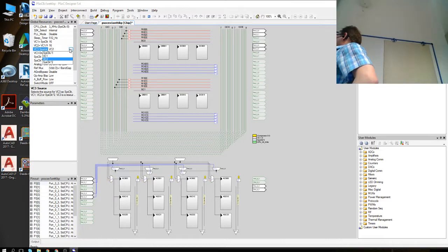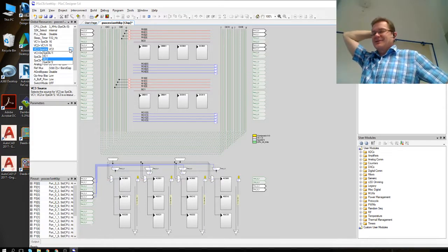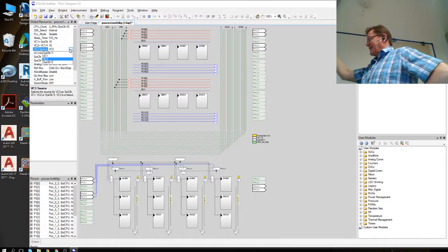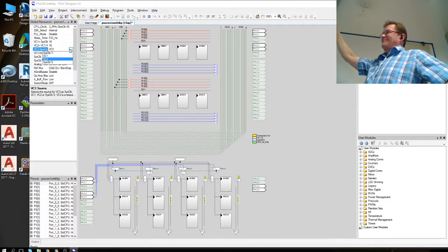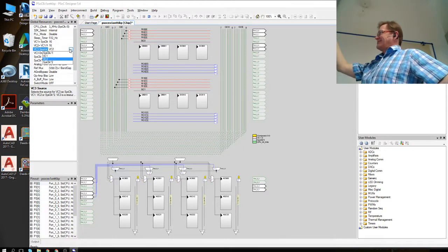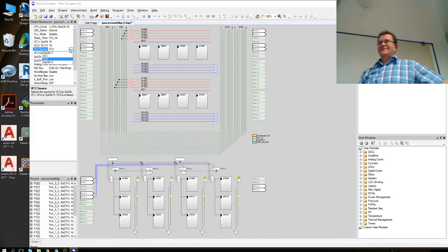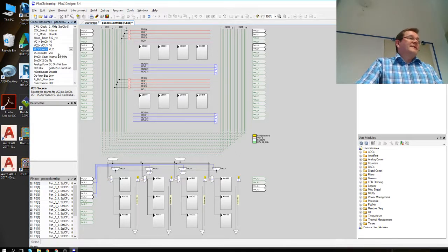System clock divided by 1.5 was something I was thinking about. So how to divide by 1.5? Well, first you multiply by 2 and then divide by 3. Yeah. Okay, and this is an 8-bit divider.